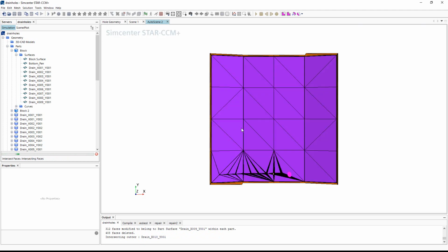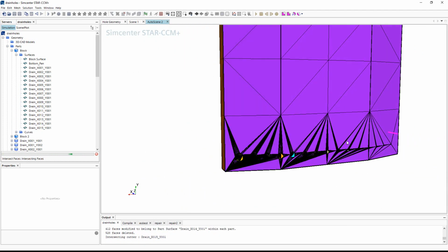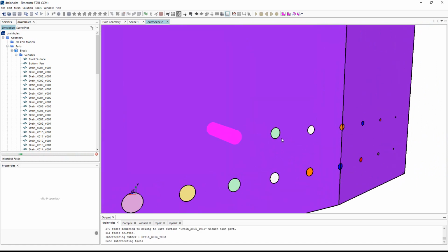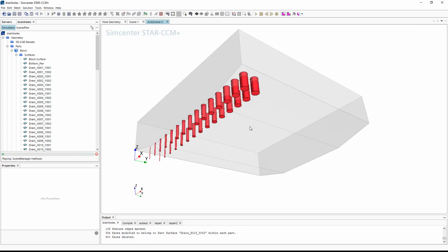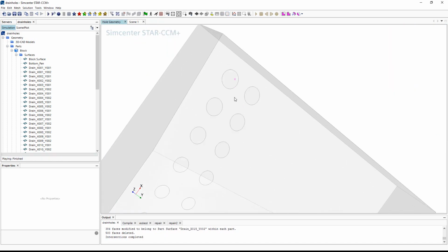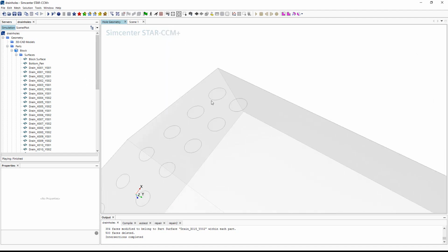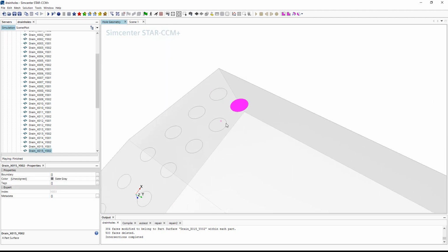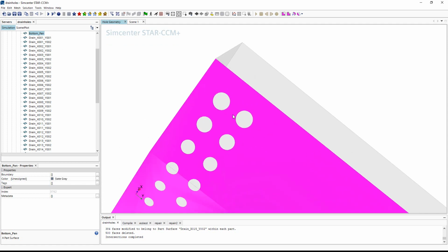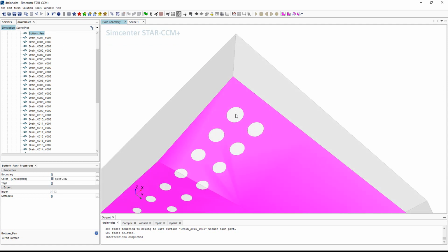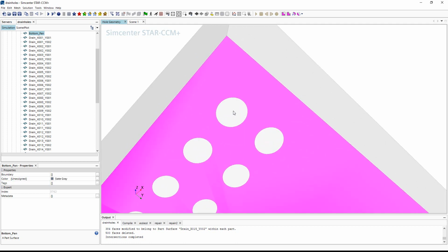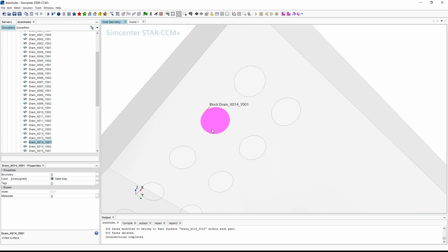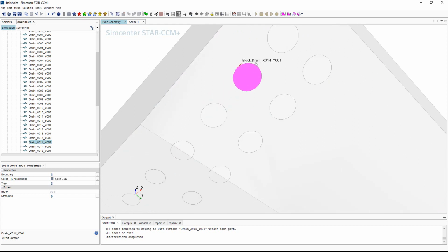Then a new scene will open, and we can see our cuts being made. Right, and all that's really happening is literally the same thing that happens in a surface repair operation, where you grab these faces, add them to the first set, you grab the cylinder, add them to the second set, perform the intersect, and then I use a geometric range to grab the faces inside the circle and assign to them the same name as I had on the cylinder.